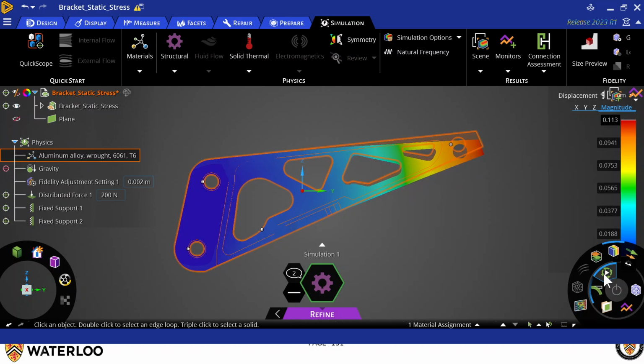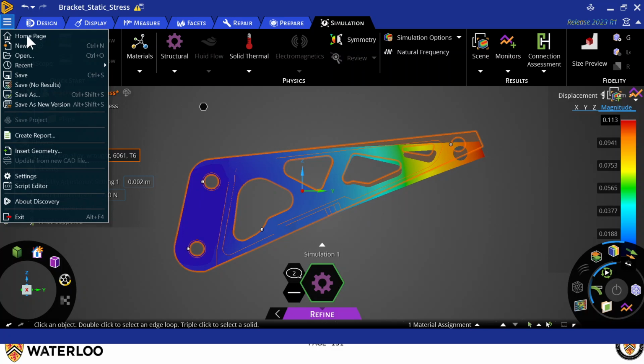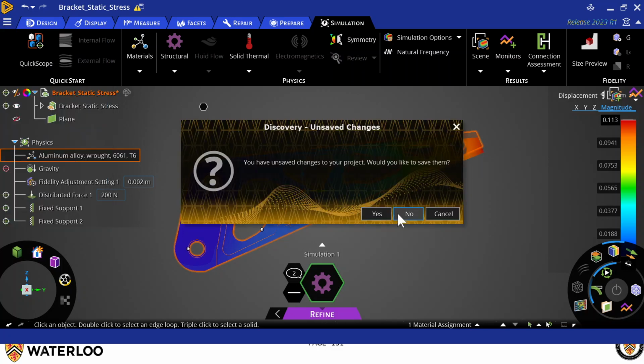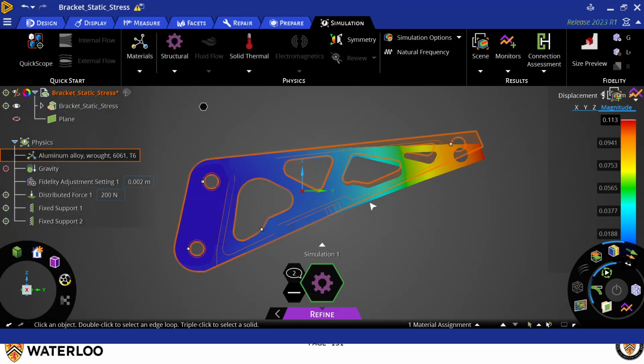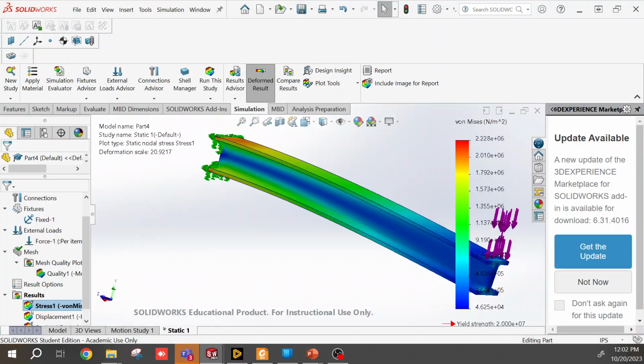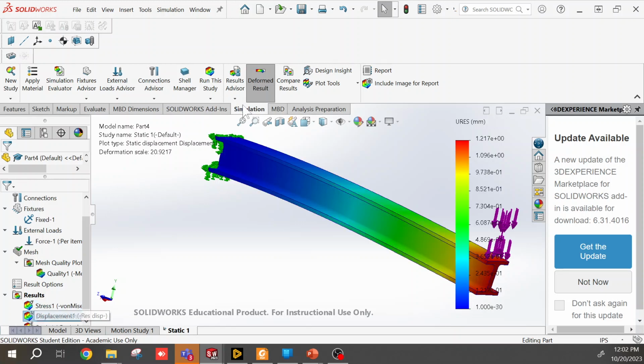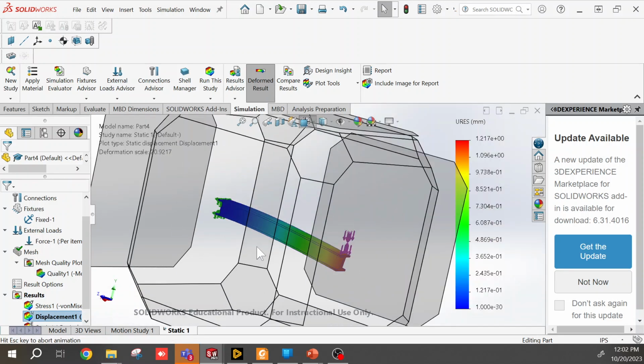So we're probably going to ask the question, the way ANSYS works is a little bit different. But you can see that here's another example of something, and there's a bunch of different example files in ANSYS that you can work with as well and do some static analysis in there. Let's go back and check to see if our SolidWorks simulation is finished. You can see that it has our nice I-beam profile, has a lot more displacement now. So let's check what that displacement is because we've cut out a whole bunch of material, and we will orient the image.